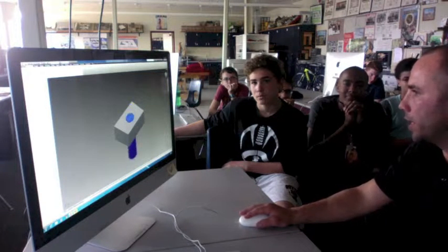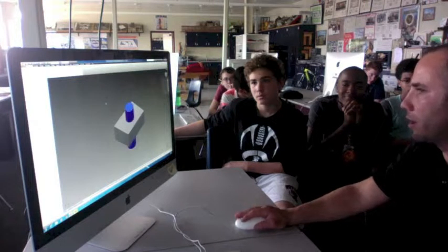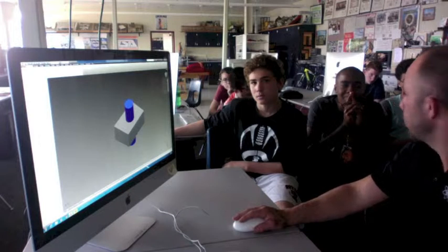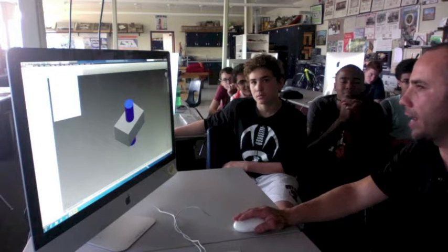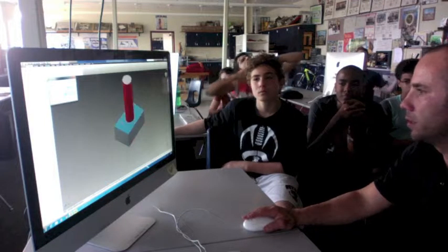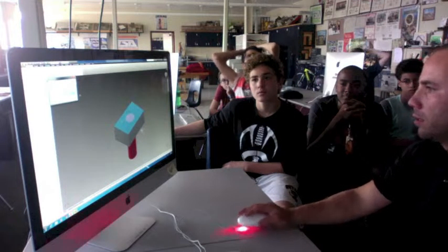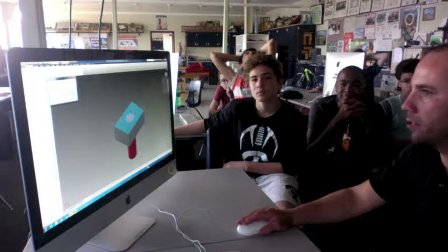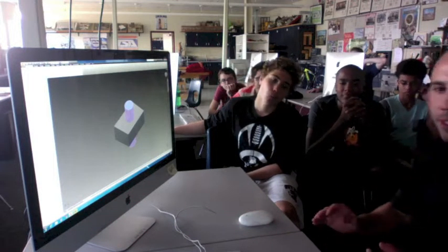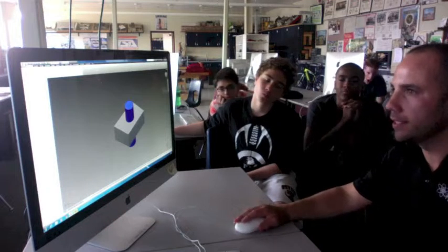Okay, there is a way to constrain that face to each other if I wanted to, but I want to be able to make it move and keep it inside their line of axis of symmetry. But if I wanted to make the tops equal, I could do that too. But I'm going to cancel it. I want it to be able to move. Now, since it's an assembly, it's a separate file type. I have to save it accordingly. So I'm going to save it as block assembly.